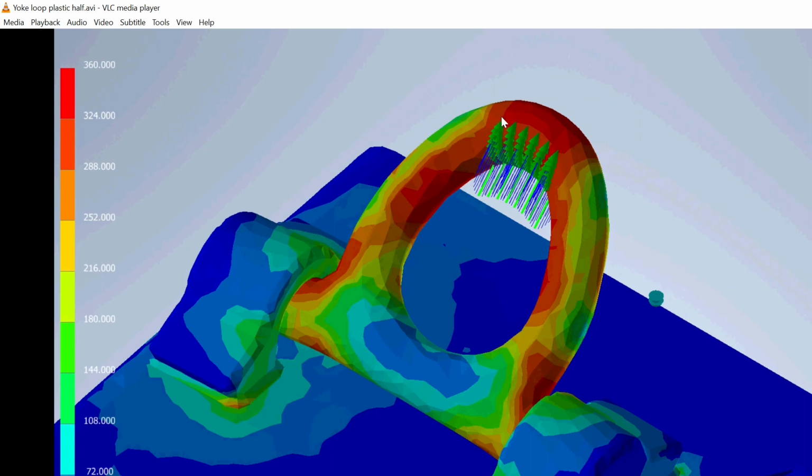But that's how it works technically. The load is multiplied and the strength of material is reduced, so you have double safety, and about 30% extra load was applied and about 30% of material strength was removed for this ultimate limit state.